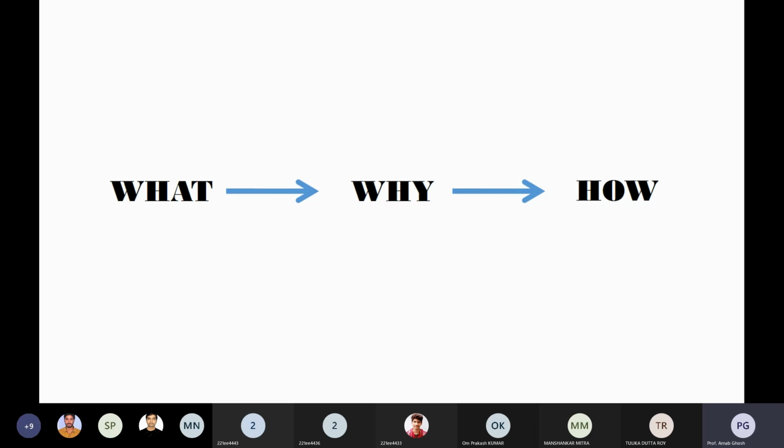Another one is steady state stability. Steady state stability is related to how much regulation you can achieve from your proposed switches and converters. There are different types of converters, so how you design your system, how you are able to design the optimal regulation of your system. There are three types of regulations: input regulation, load regulation, and temperature regulation. Input regulation means line regulation.